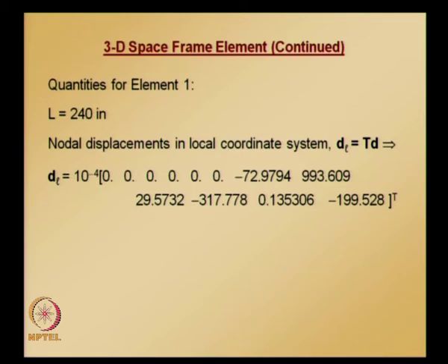Once we obtain the displacements in the local coordinate system, we can calculate axial forces, shear, moment and torsional moment at both ends.